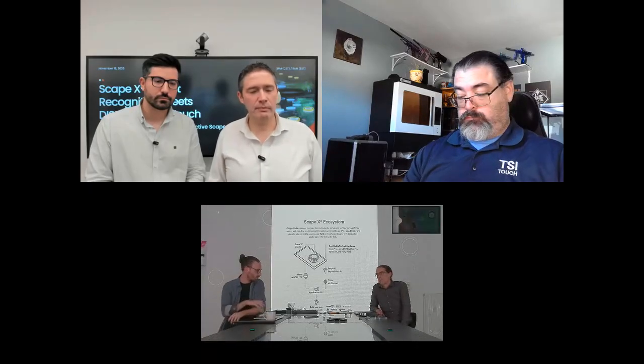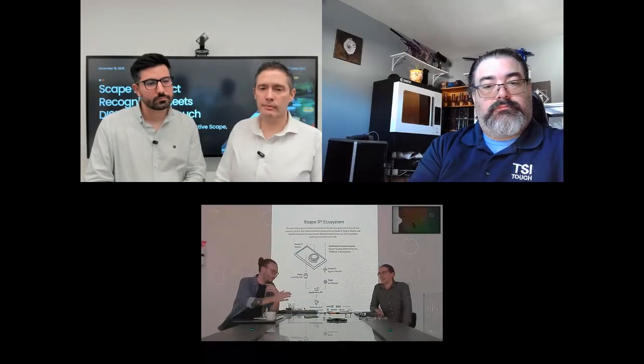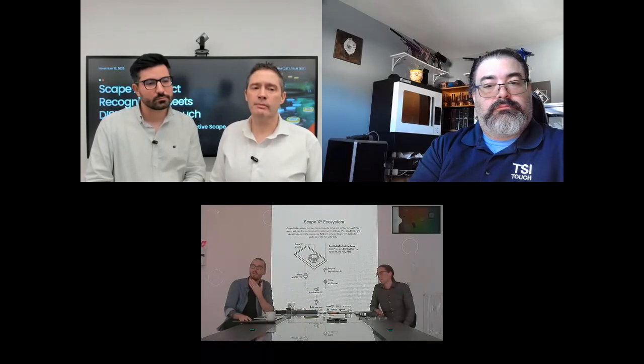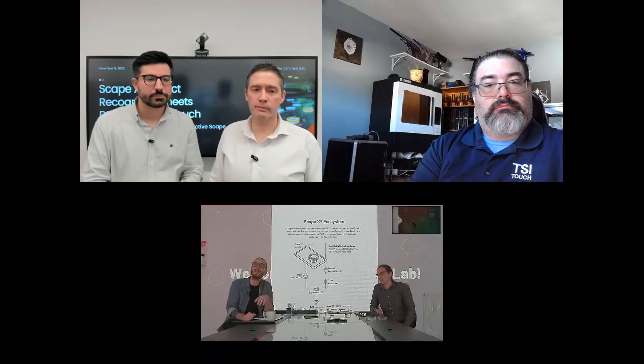Maybe just really quick to that, we could differentiate the phones just by their capacitive effect, but you could of course have 3 people coming with the same iPhone to a table. So what we do there as well is we use the motion sensor inside the phone to set the special ID with each phone. So you could also come with the same mobile device, having the same PCAP effect. But since the phone also speaks via TUIO 2.0 with the table application, with the motion sensor, we can set special IDs independent from the PCAP effect.